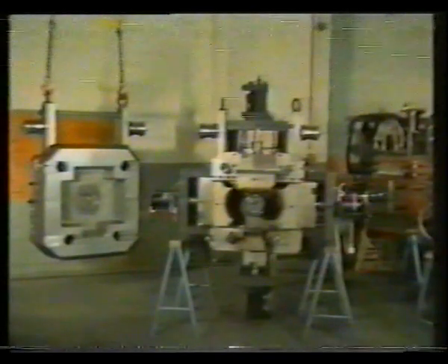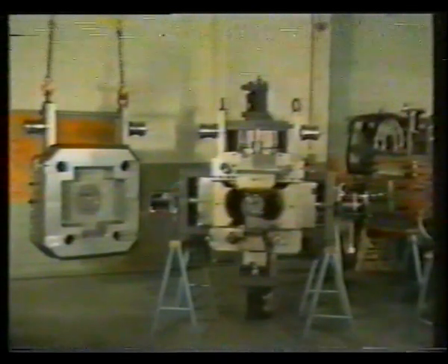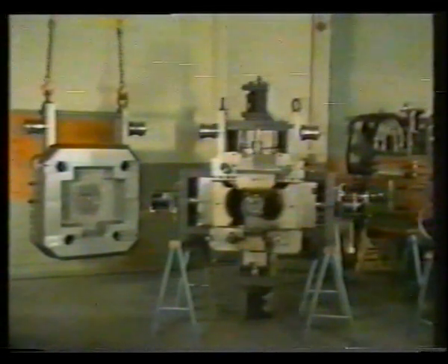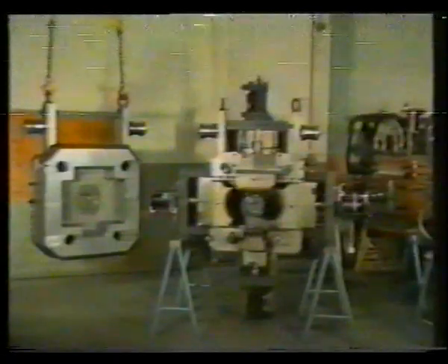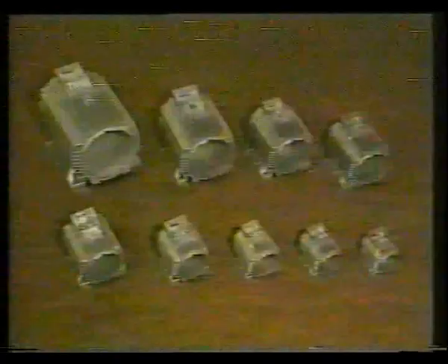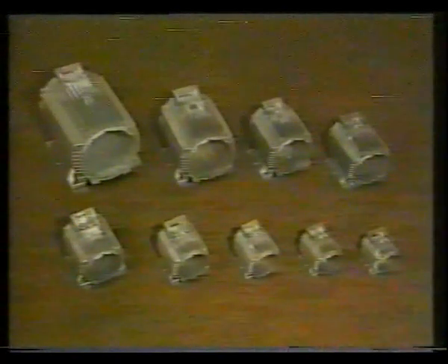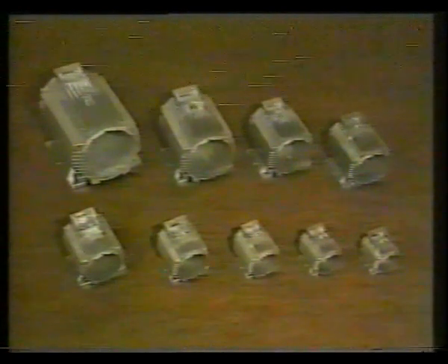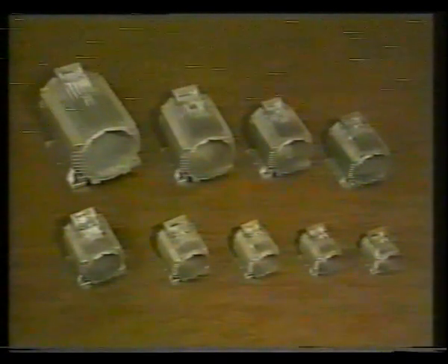The die design makes provision for automatic stator extraction by means of a pick mat handling unit. The method of casting housings favors automation, as the weights to be handled are less than 15 kilograms. The design and manufacture of the dies for the 9 different stator sizes are all based on the same principle.